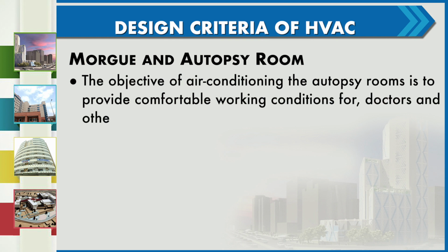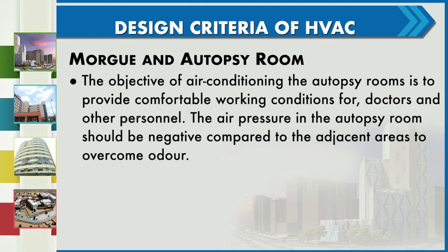The objective of air conditioning the autopsy room is to provide comfortable working conditions for doctors and other personnel. The air pressure in the autopsy rooms should be negative compared to the adjacent areas to overcome odor.